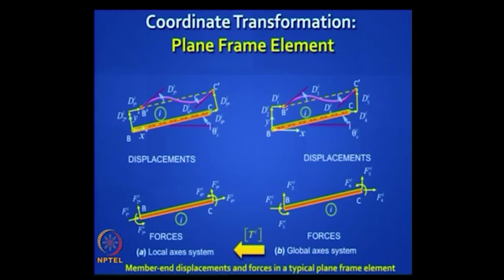If you take one of those ends you will find that it forms this familiar transformation, the rotation matrix, where you have cos theta, minus sin theta, cos theta, sin theta, and you have 1 corresponding to the 3rd degree of freedom, because there is no need to do any transformation with respect to the z axis, because we are talking of rotation about the z axis.